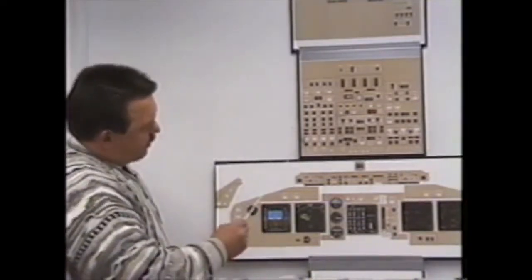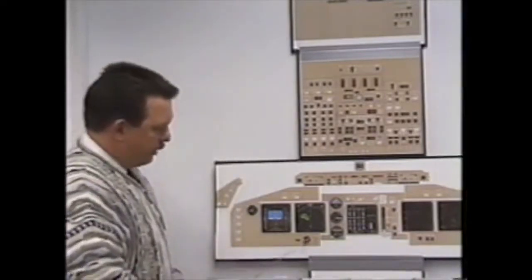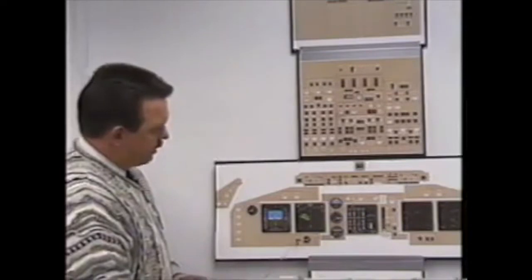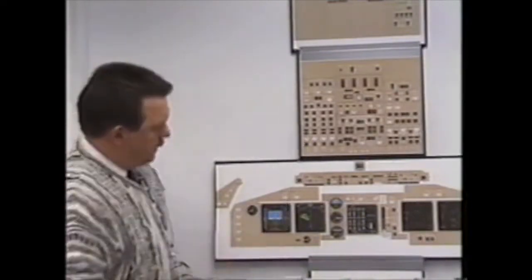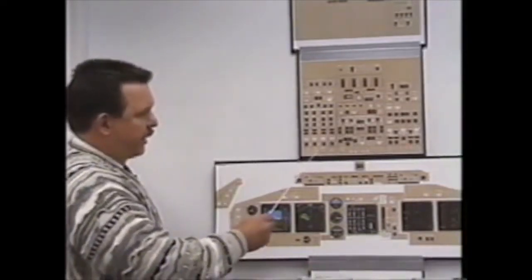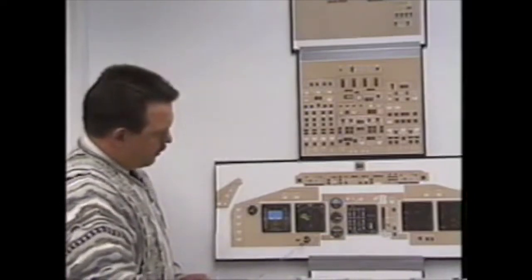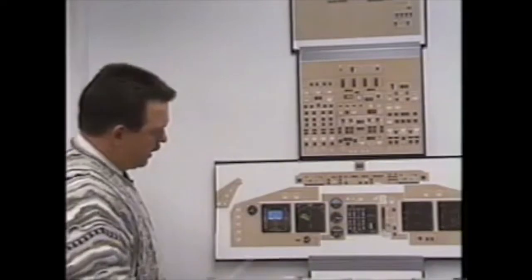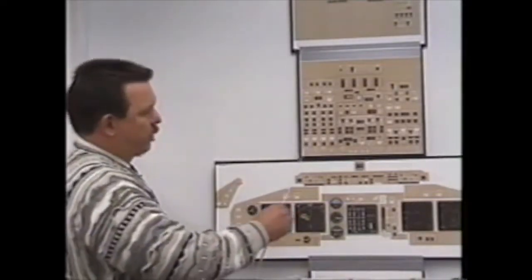I then reach up and pressurize hydraulic System 1. System 1 is pressurized. Again, that will not bring up the brake accumulator gauge. The brake source light is still out, indicating the brakes have gone from 2 over to 1. I then reach up and pressurize hydraulic System 4. System 4 is pressurized. That will bring the pre-charge up to system pressure, which should be approximately 3,000 psi. The brake source light is out, indicating the brakes have gone from 1 over to 4.